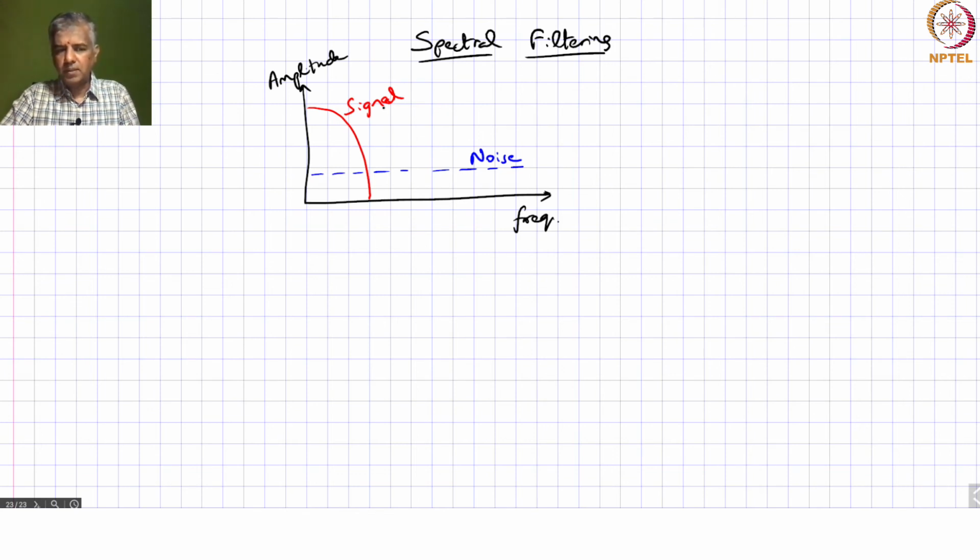If that is the case, then why do we need to have a receiver with very high bandwidth? I mean, your photodiodes normally have a bandwidth on the order of hundreds of megahertz easily, and your receiver, your transimpedance amplifier, could also support tens of megahertz of bandwidth.